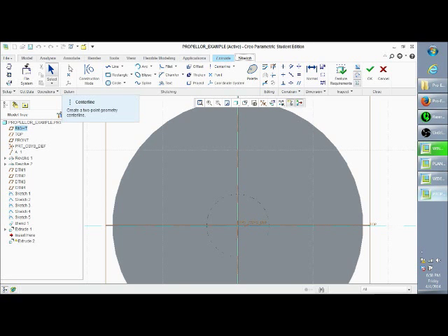You cannot use that center line now, and the center line I'm making now will not be used to rotate around. This one will be used more as a reference, which will not appear when I'm actually modeling the shape. So I'm going to click this, make sure that little vertical constraint is active, click it, and then leave the tool.